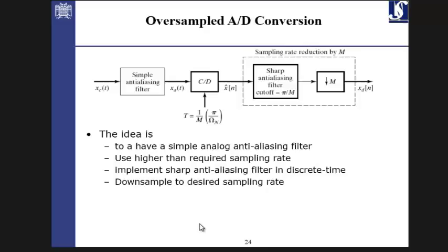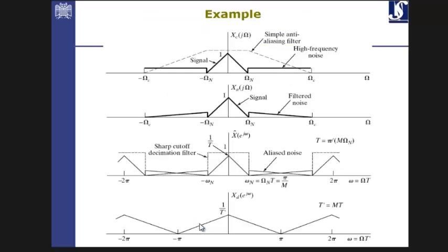What they do is design something more relaxed, take the oversampling here, but they need an anti-aliasing filter here in digital form. That can be implemented, no problem. And then they do the downsampling. The upsampling and downsampling is what I'm going to explain in the next slides. It's just for your experimental knowledge, but I will go through the down and upsampling and changing the rate of sampling.